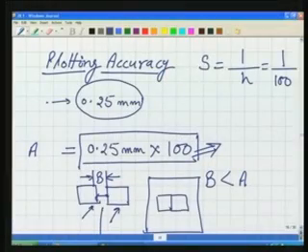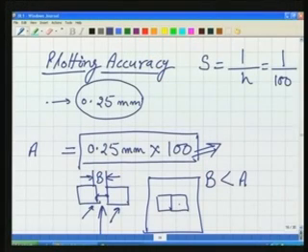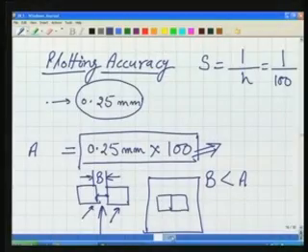Or if the separation between two objects, as we saw here, is less than the plotting accuracy there in the ground, we cannot show these two objects separated here in the map. So, we should always keep in our mind to what extent we should go and map. This is very important, this plotting accuracy.